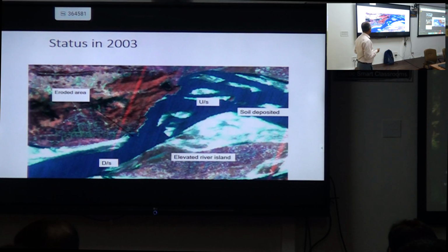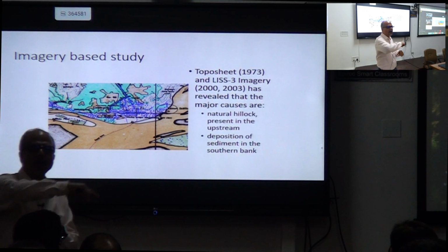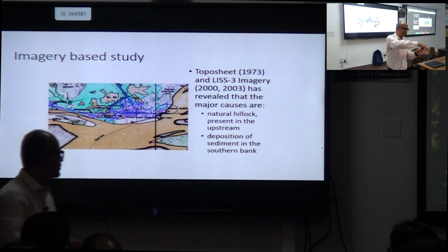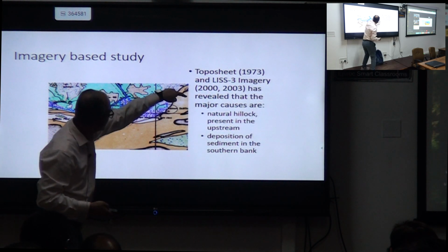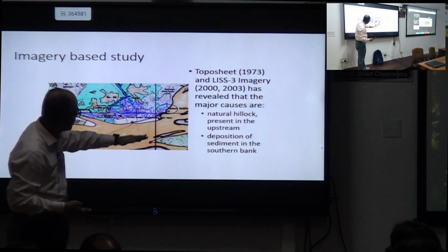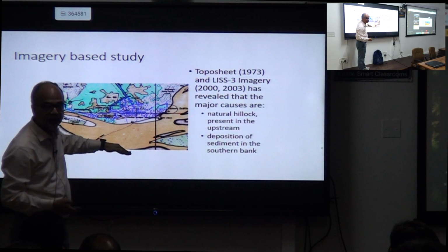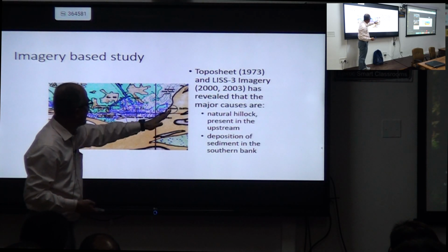So we rushed to the point, and I was of course trying to understand what was happening. We analyzed this. Going there, I could see that it is a huge whirlpool. The river is flowing from this side, coming like this. Generally we know that erosion always happens on the other side of the river. When the current is like this, it will be eroding this part. But erosion has happened here. That is the most interesting point.